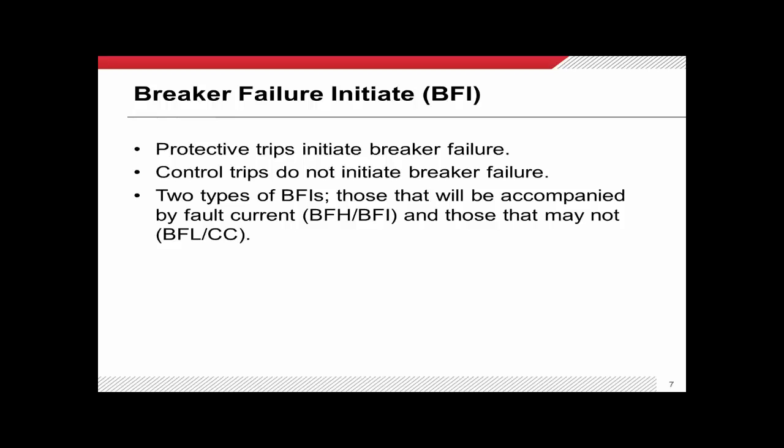And in the old days, not too many people would worry about this because it took so many various discrete devices to implement a breaker failure scheme that they generally liked to keep these things simple. But with modern programmable relays, it gives us a lot more opportunity to really fine tune how we design these schemes. And so in a couple of classes, I'll show you an example of a breaker failure scheme that actually takes this into account.